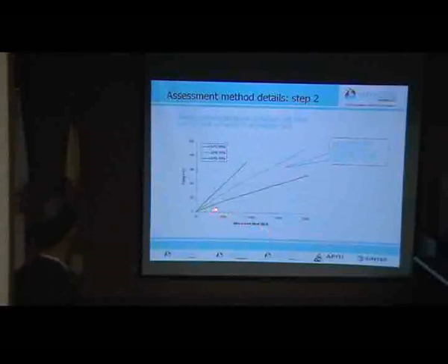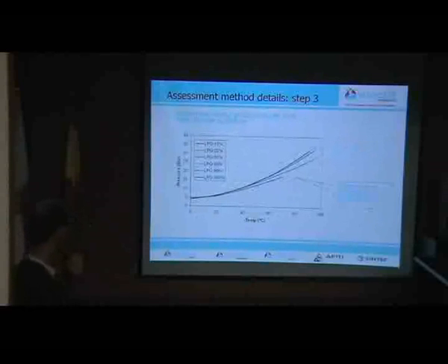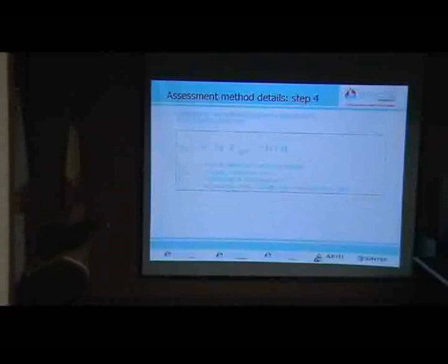So there are some relations given between the absorbed heat and the temperature for different LPG fillings. They just depend on the thermodynamic properties. And then from the temperature you can determine the pressure, the vapor pressure in the tank. And from this vapor pressure you can determine the membrane tension, or the stresses in the tank shell. So this one is an important one.